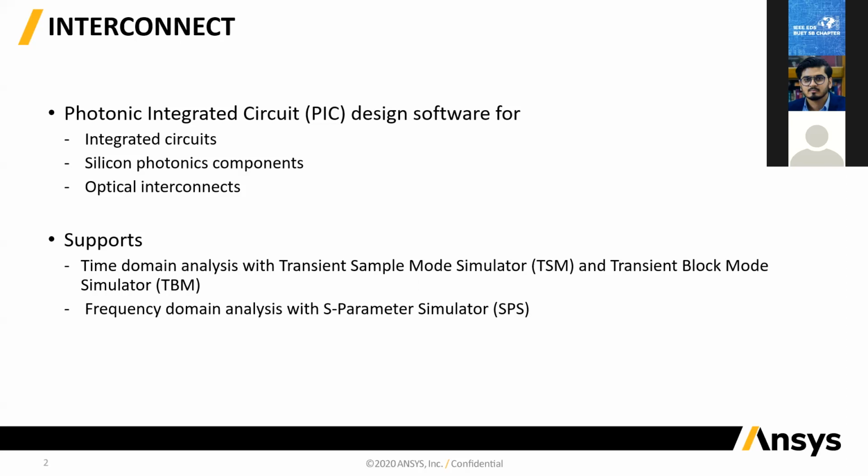So you can bring your building blocks into the interconnect schematic editor, hook them up, bring in your sources like lasers and photo detectors for detection, and then run a simulation of the full circuit. Interconnect allows you to perform both time domain simulation and frequency domain simulation.